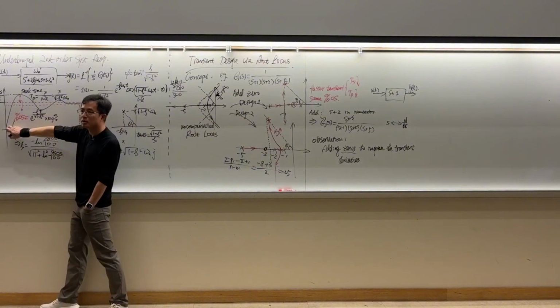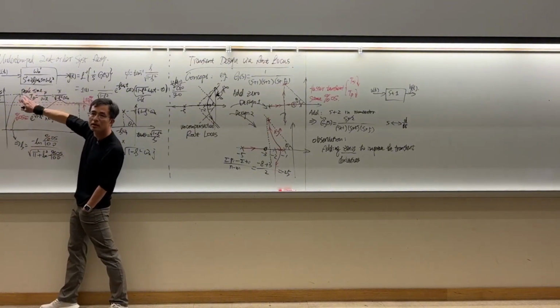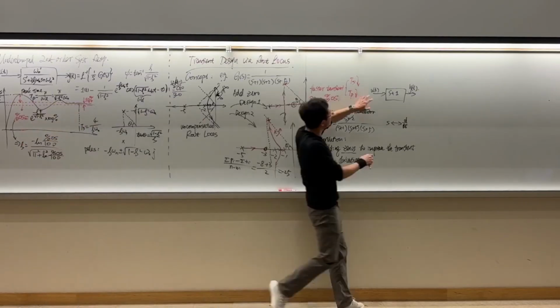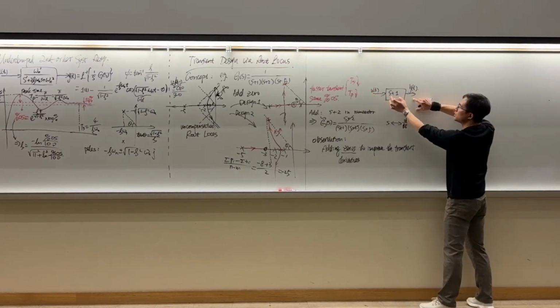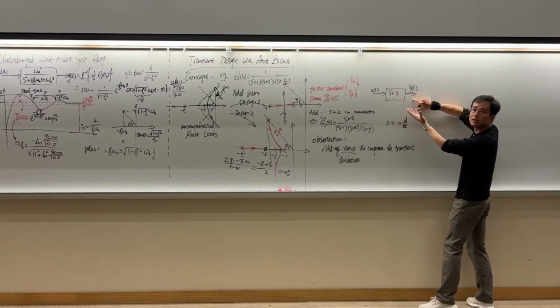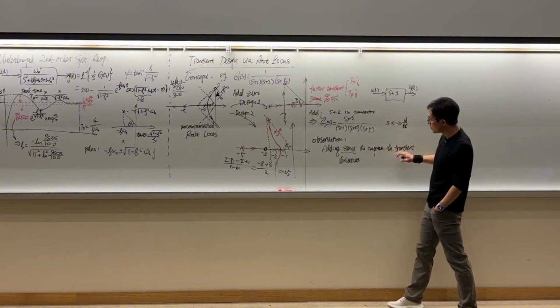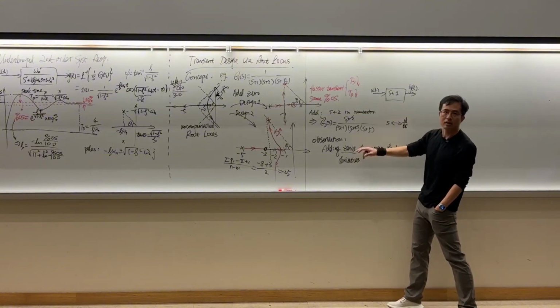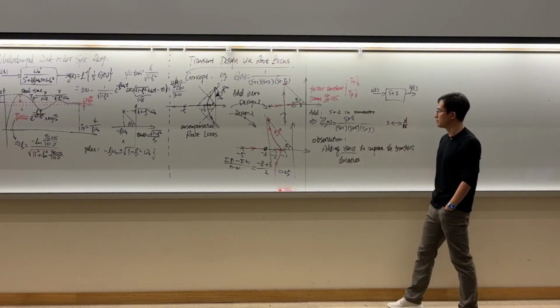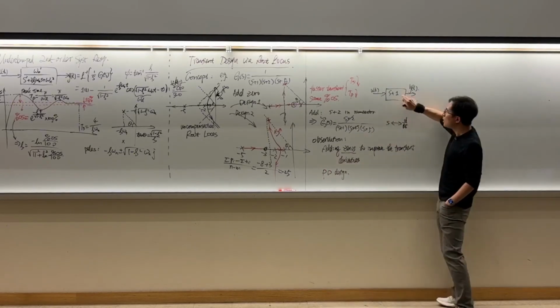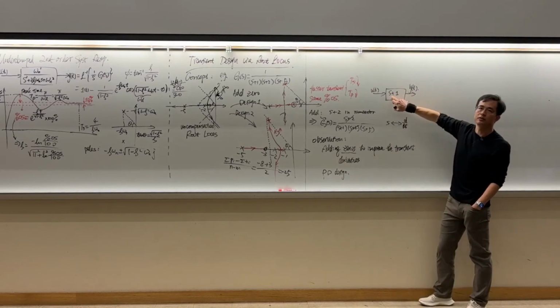If the input is increasing, what's the derivative going to be? Positive, right? So that means if the input is increasing and you add a derivative term, you're going to accelerate the increase because it has a positive slope. So that's the logic behind adding zeros to improve the transient: adding some derivative terms in the time domain. This is called PD design, proportional derivative design.